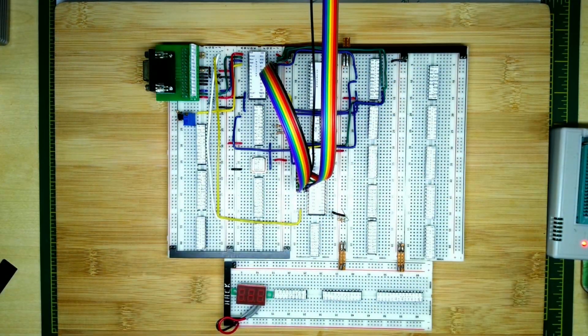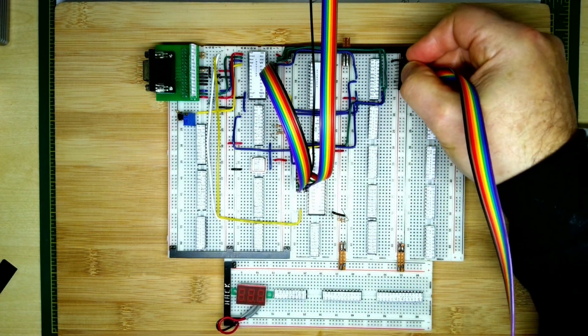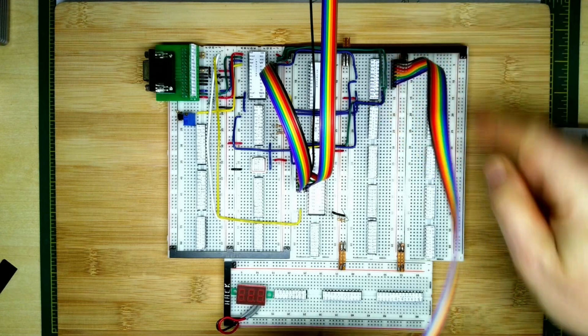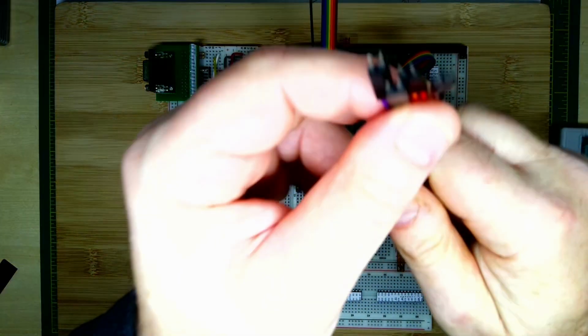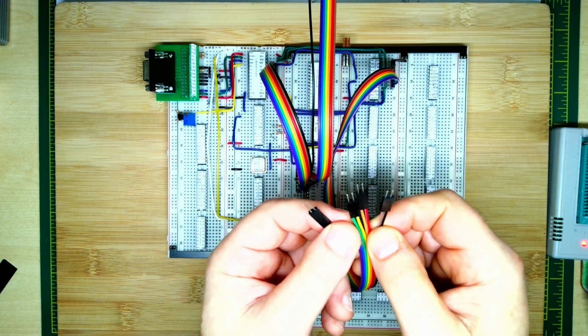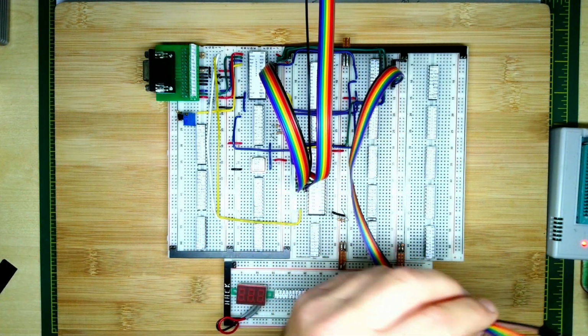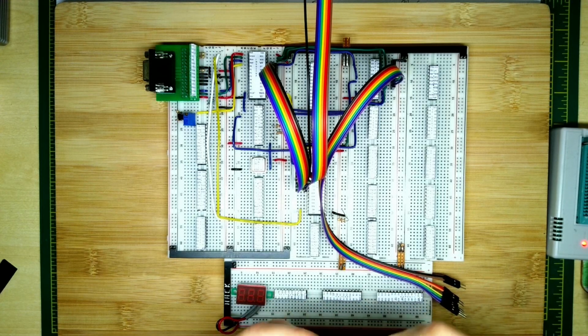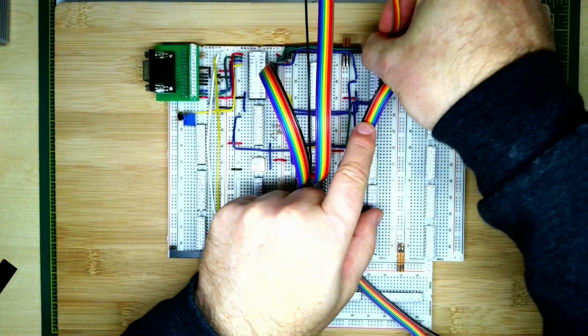Then we just need to do the address lines. So I've got the address lines 0 to 7, and we're just going to plug those in up here. Now there are also going to be address lines down here, so this is probably going to move down here a bit later. You can see here the main address bus is using these sort of power strips, so they're in twos, so I've actually got the connectors done in twos there. And then finally we've got the upper A8 to A11 address lines, and we're just going to plug those in over here, and we'll need to find somewhere to plug those in.